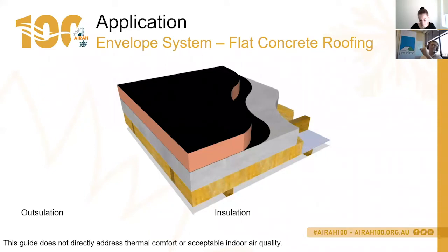And then we can look at that system and say, well, is there going to be any problem? Is that concrete going to get cold? Is it going to increase moisture content in that concrete? That can all be looked at using DA07 criteria and hygrothermal simulation software.